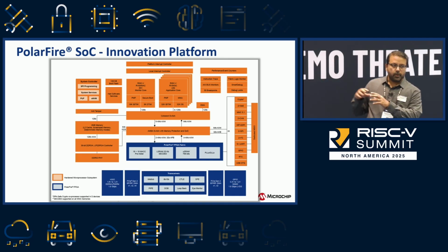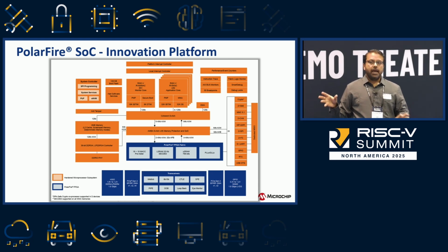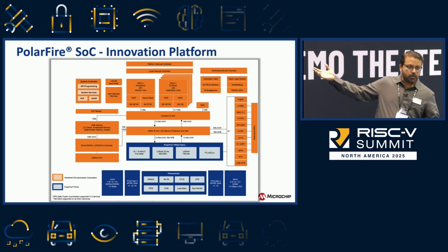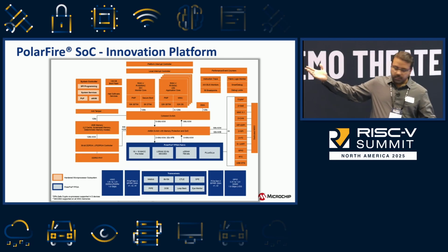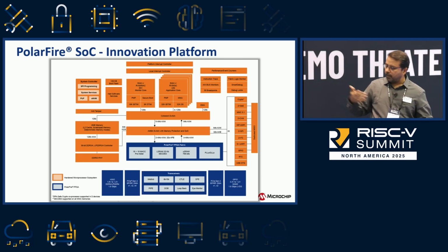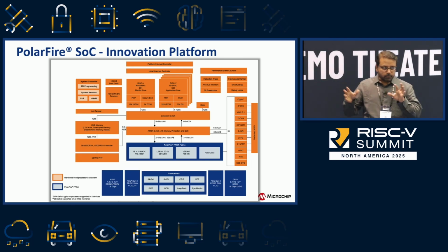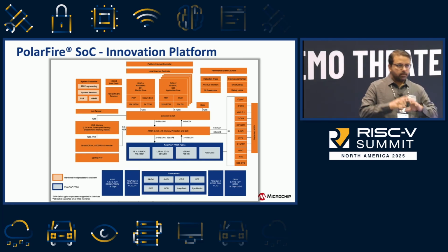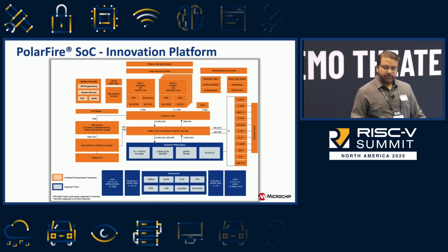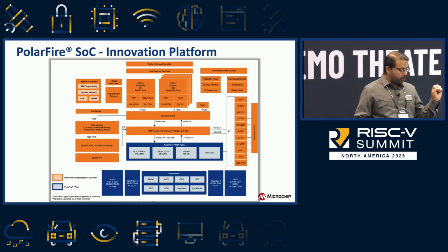So you get to develop your own custom hardware on the FPGA fabric, and then you can control and communicate from the microprocessor subsystem. The microprocessor subsystem actually runs Ubuntu in the Beagle board, all right? So these two together form the bulk of what PolarFire SoC FPGA is. And we wanted to look at developing a system like this where there is some amount of serial processing. You may want to run like a video player and then control a whole lot of LEDs. We thought that an SoC FPGA was kind of ideal to port something like this.